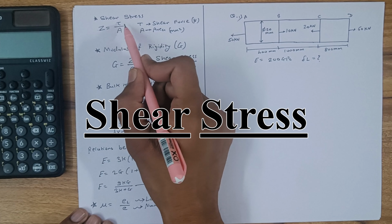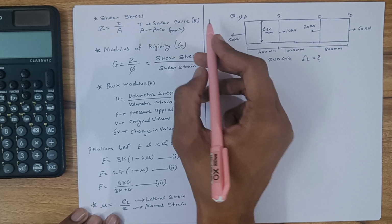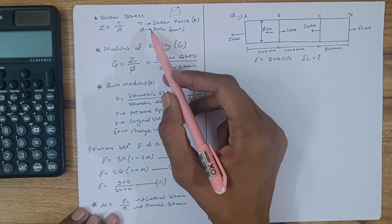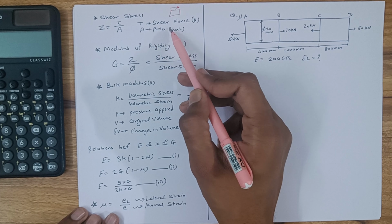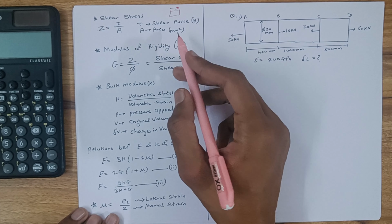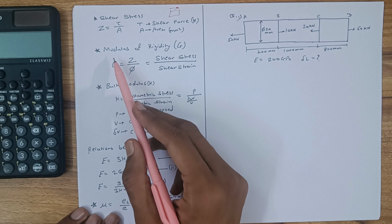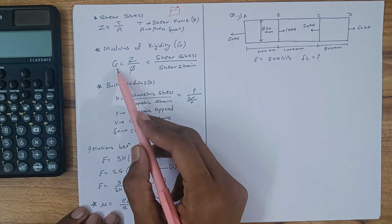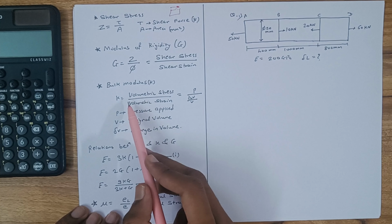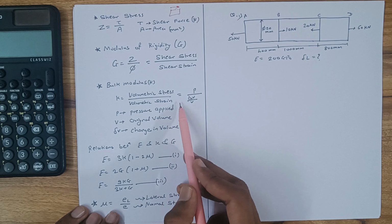Now the shear stress. Shear stress is equal to shear force upon area. Shear force is parallel to the direction of the body. Shear force is in Newton and area is in mm square. So the unit of shear stress is also Newton per mm square. Modulus of rigidity. Modulus of rigidity is equal to shear stress upon shear strain. Bulk modulus is stress upon volumetric strain.